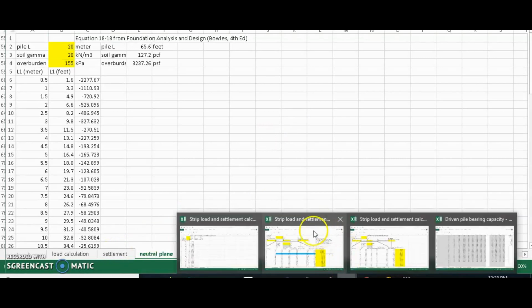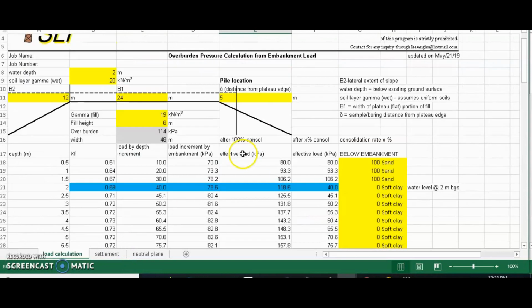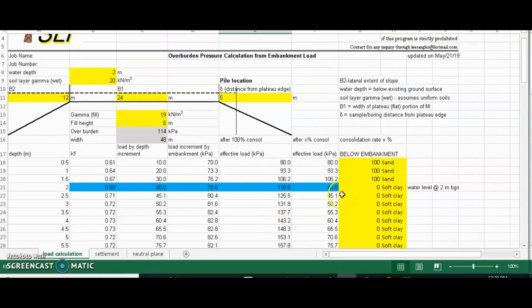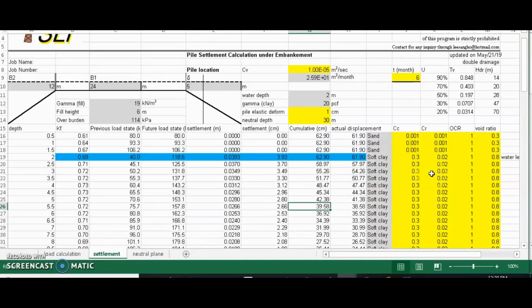And then I will show you, if the pile is located on the hillside, not the center of the embankment, you need to use a different spreadsheet. In that case, the sections are the same as before, and then you plug in the soil type, and the different degree of your starting point of consolidation degree. And you specify the embankment dimension here, and then there's another tab where you actually do the calculating.